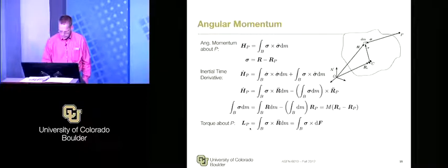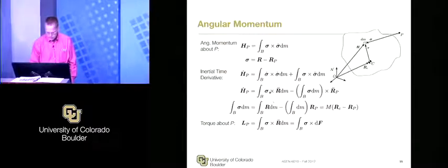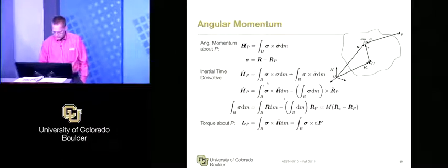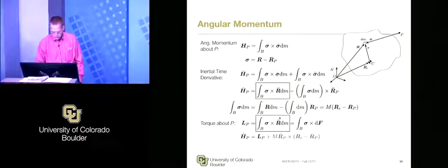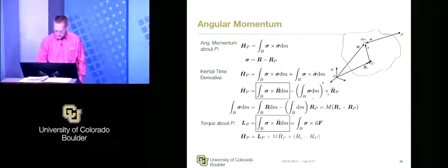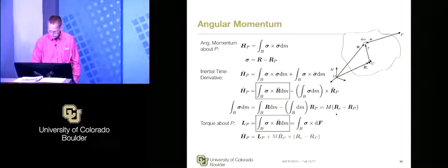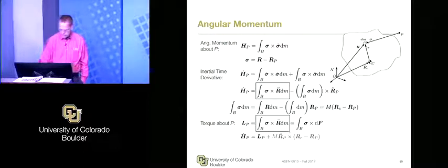The next thing we're going to look at is what happens with the torque. The torque about this point P is always going to be the force at this point, which is mass times acceleration. That is the force. The moment arm crossed with that force. That's one way to write it. And let's see, up here we did see a sigma cross that. That's basically going to be your torque expression. So plug that back in, you get this plus this term crossed, yeah, so m times this crossed with rp. So that's what gives you this extra stuff.